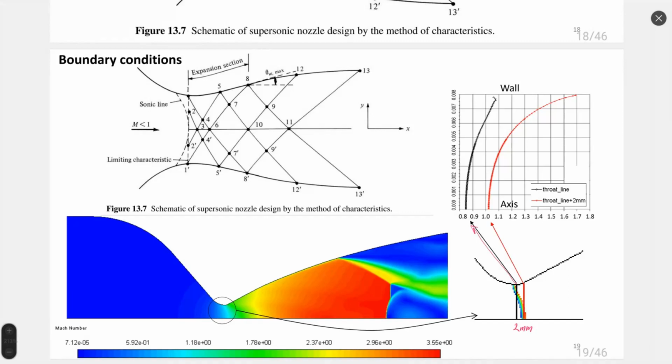But the method of characteristics is more fundamental, because it uses equations of conservation, and a parabolic function is just an approximation to this method, not exactly solving the original equation system. It is the same as, for example, when we calculate a drag coefficient by CFD method, and we use an approximation of this drag coefficient from some experimental data, some empirical function.